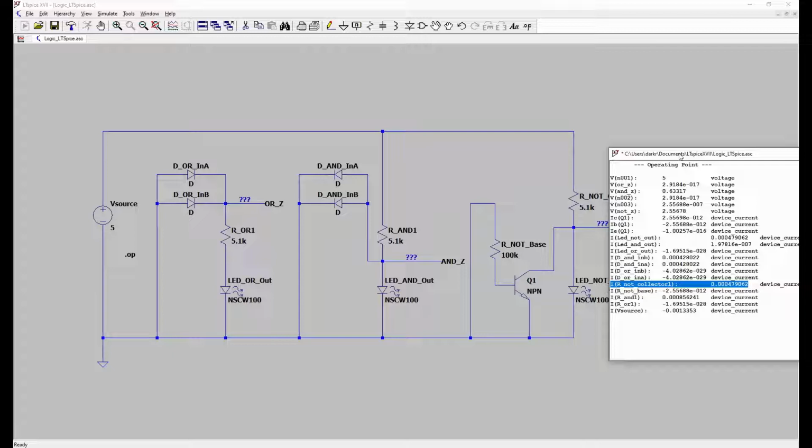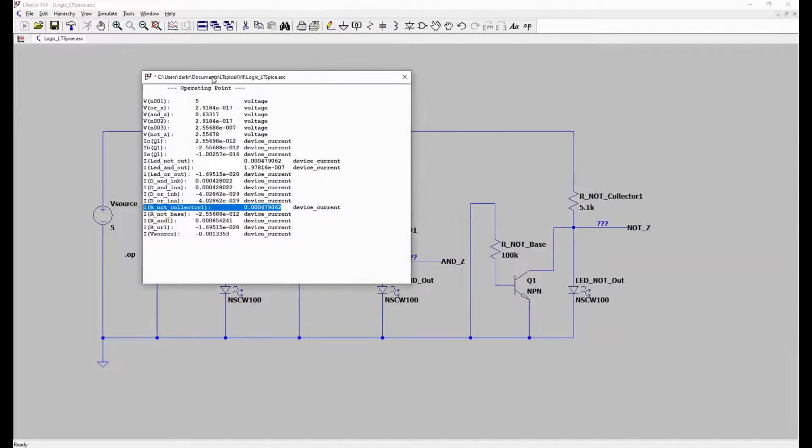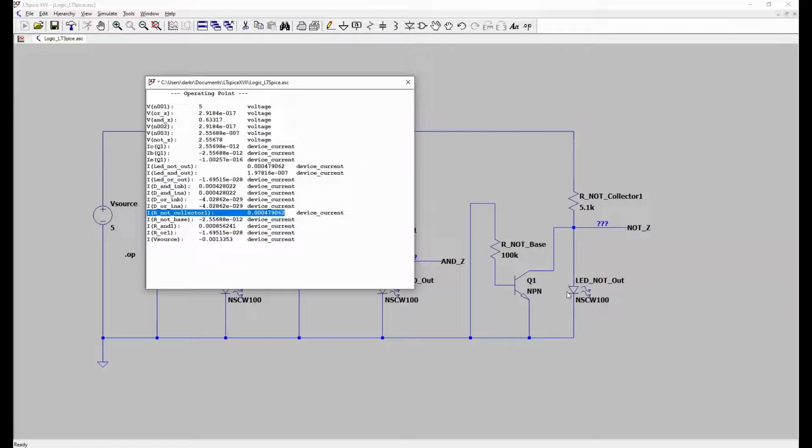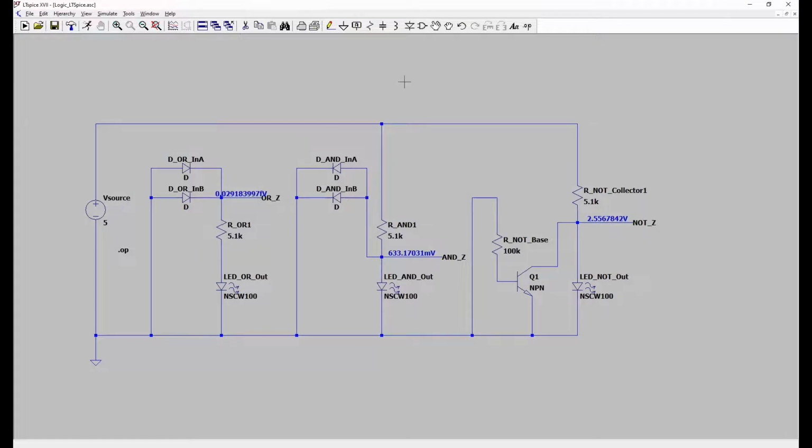This is good to know for a number of reasons, not the least of which is that this LED has a voltage drop of about 2.5 volts, which is usually enough for any standard 5 volt input to consider it a high. We can work with this.